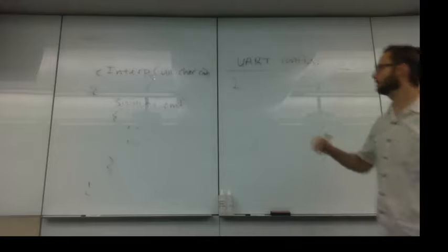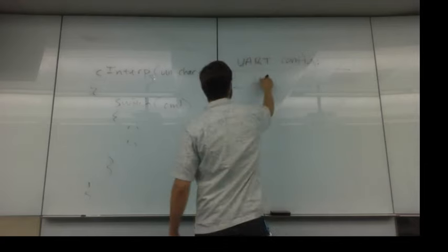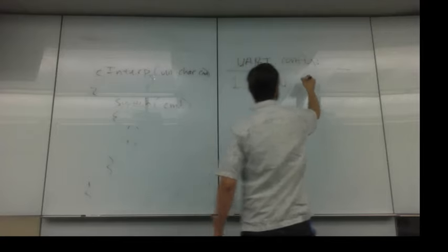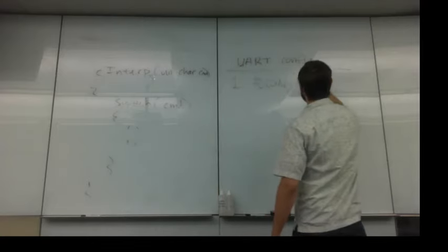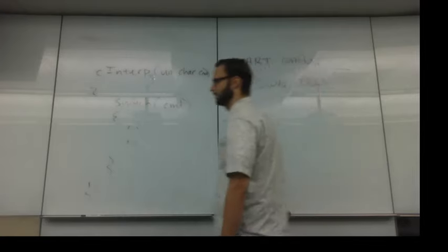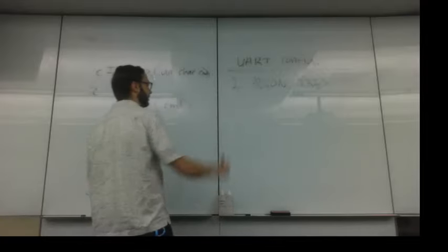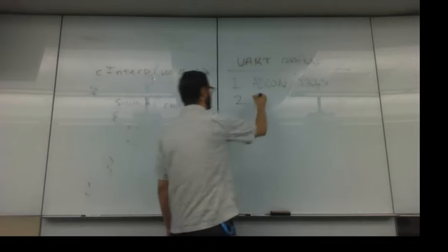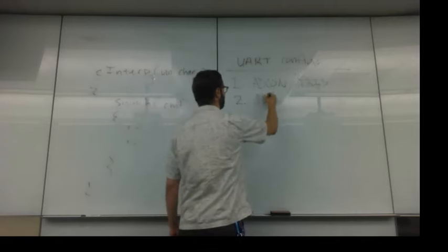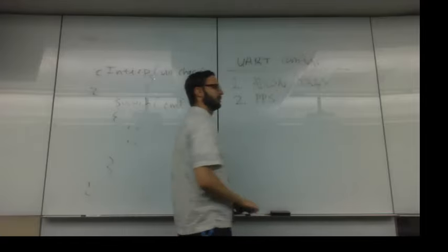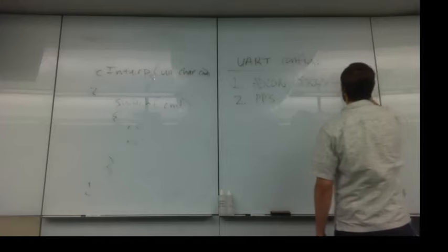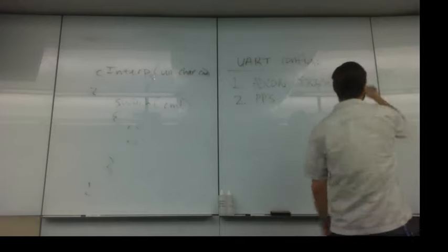Or maybe the ADCON register and tri-state registers that you want to pick for inputs and outputs. And step two, we haven't talked about this much yet, would probably be peripheral pin select. So basically you want to pick what pins you want to use for RX and TX.